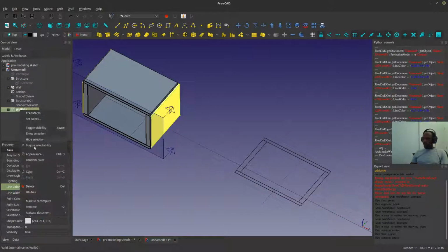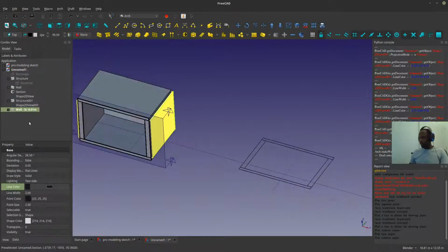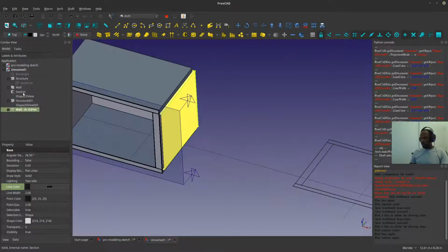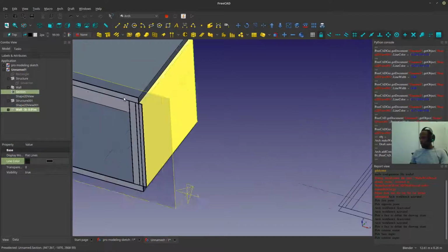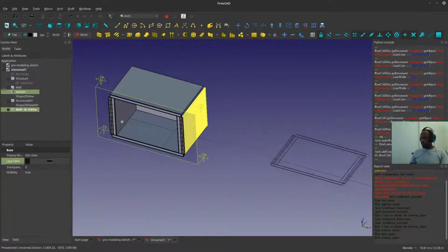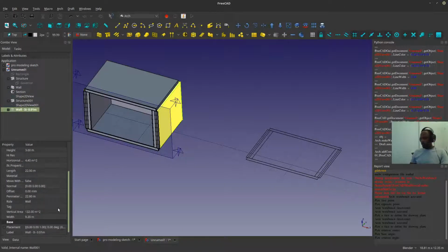I select the wall. Maybe I can rename it, I say wall dash interior wall dash, I don't know, maybe 0.01 millimeters thick. So I tell my wall, I want you to be inside my section so I can see you as well. Jump in there, so automatically it updates here, and obviously I can see it here, right? So now I tell it, well, now 0.1 millimeters. Where are you? Width 0.1.